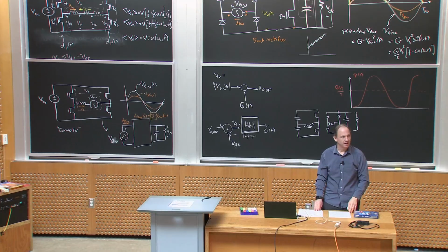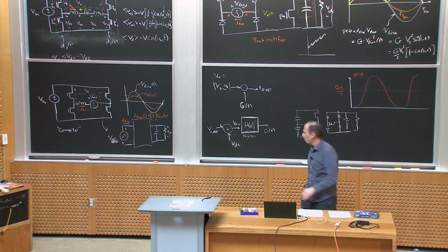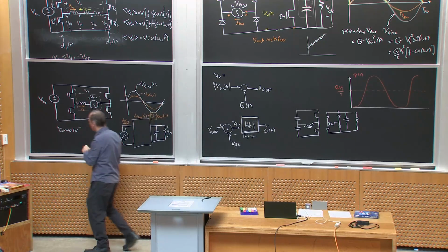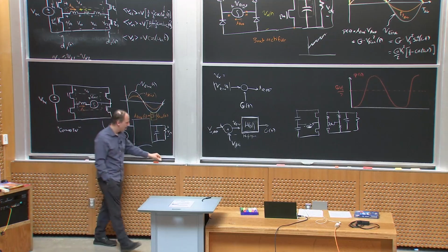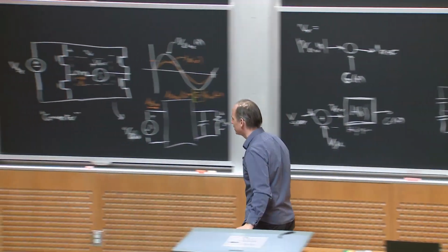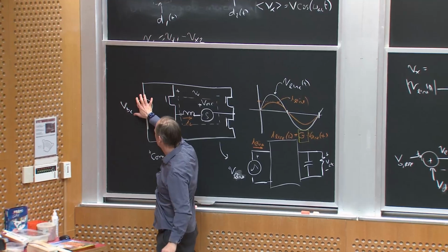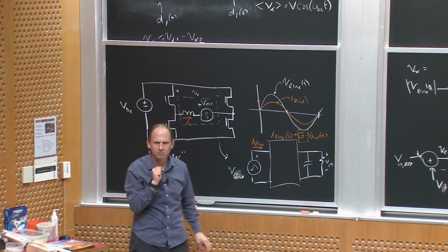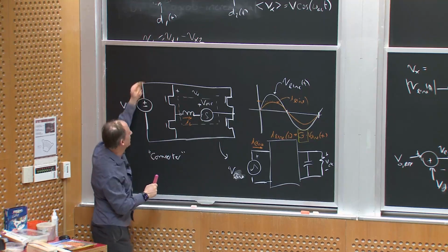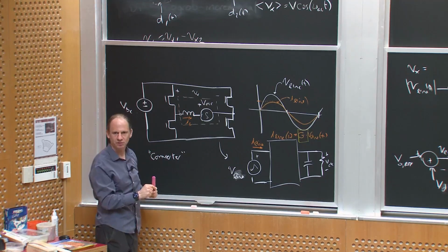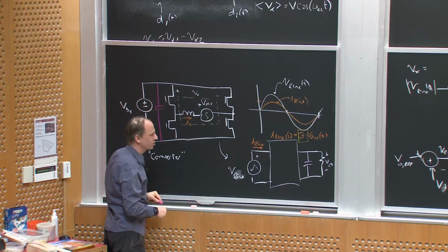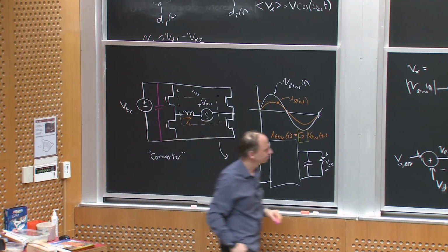That brings me to my next point, which is the following. When we talked about inverters, okay, I kind of brushed over, I just said, oh, I have a perfect DC source, and he's going to provide whatever I want, right? But I didn't worry how much power pulsations were coming from this DC source, right? In reality, I almost always have some capacitor here, okay?